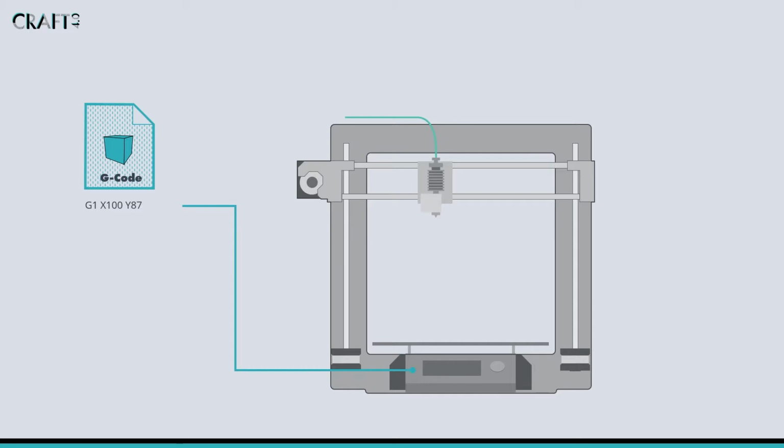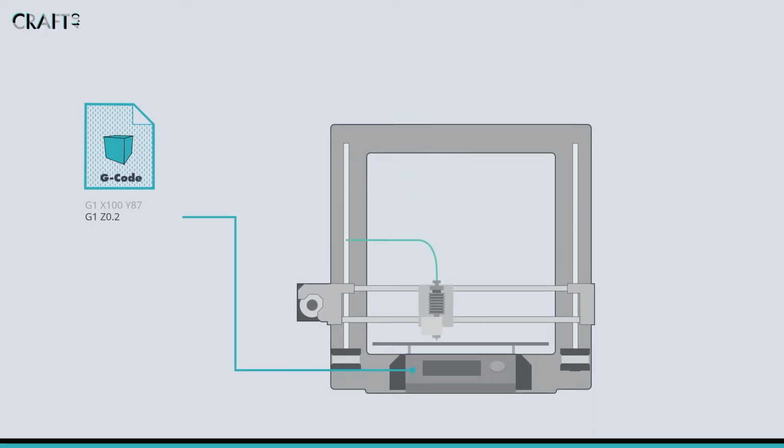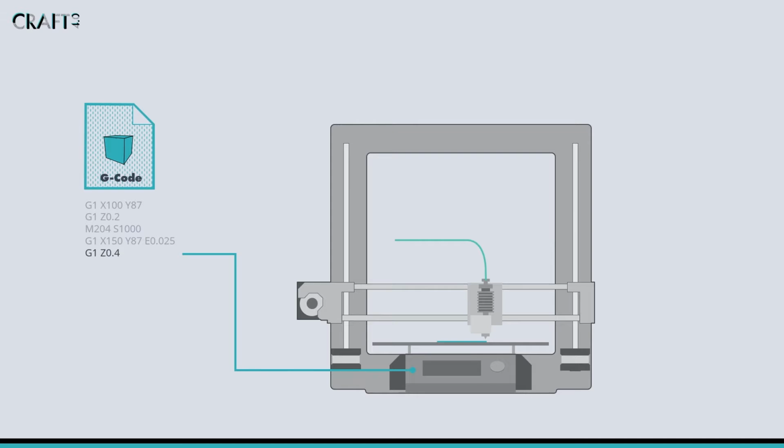Most CNC machines share the same coding language used to describe that instruction file. These are G-codes. G-codes are a text-based programming language which describes the sequence of movements and event instructions for a machine. These instructions are executed in sequence, line by line, by the controller of the machine. Each line will define a type of operation to be completed and the parameters for that operation. For example, the speed of movement or temperature of a nozzle.